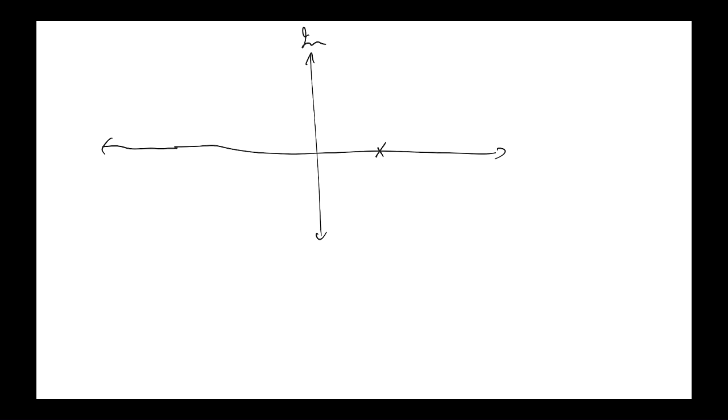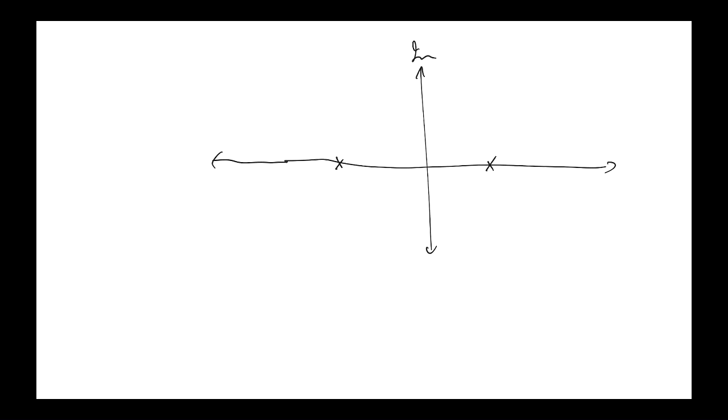I tap it, it doesn't return to its equilibrium value. And we have one stable pole. So with proportional gain, you can stabilise the system, but you'll always end up with a crappy phase margin. And so we looked at using a more sophisticated controller.